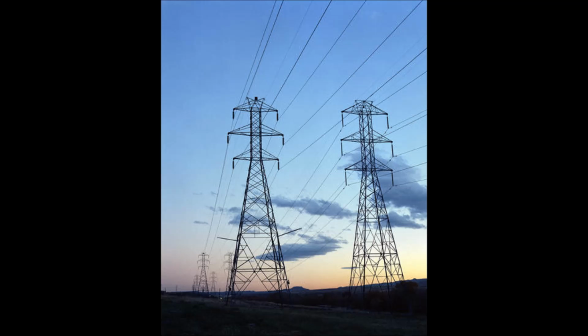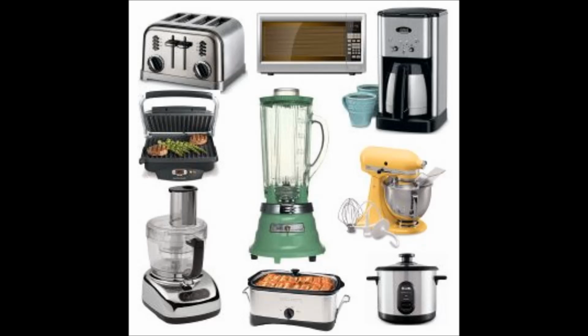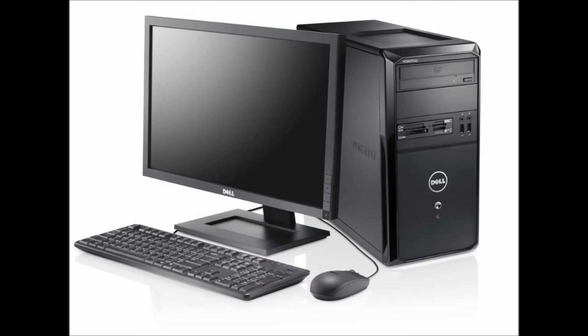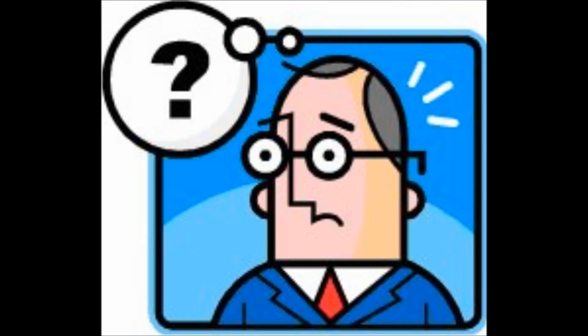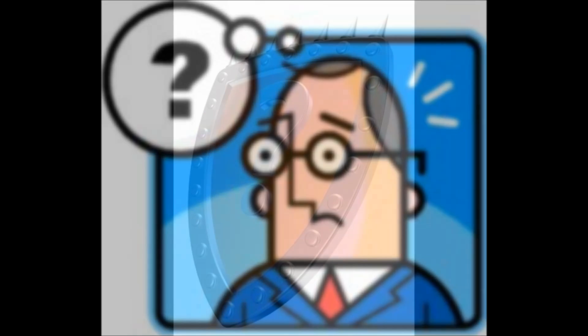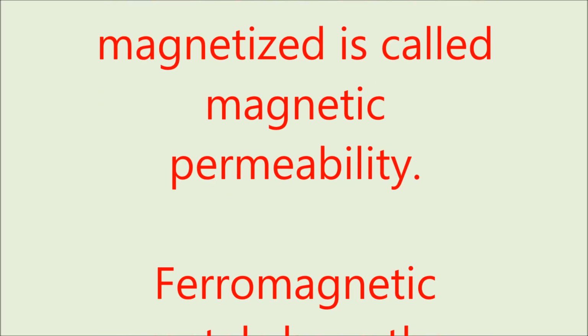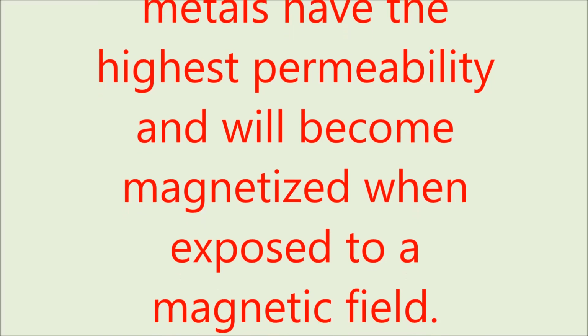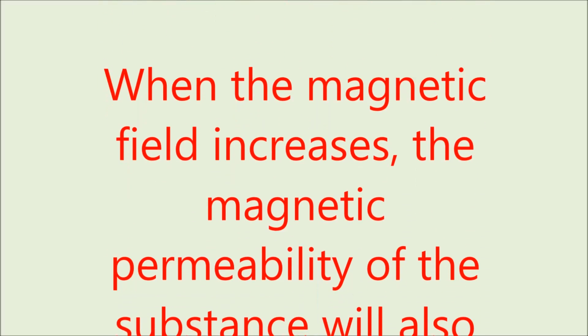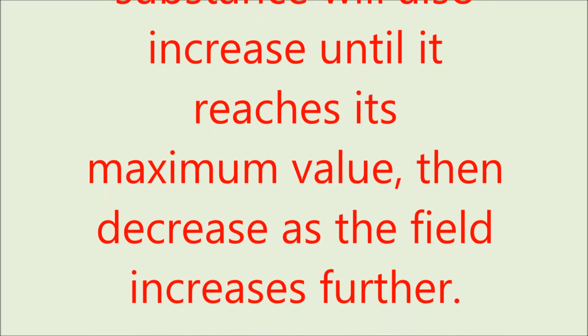Magnetic fields emitted by wiring, appliances, or electronic devices can be a problem requiring correction in the home or office. Designing magnetic shielding is not a well-developed science, and sometimes experience, careful attention to detail, and some trial and error testing are needed to produce the desired outcome. Many factors affect shield performance. Naturally, the permeability and saturation induction of the shield material itself must be chosen carefully, as well as the type of anneal. That is only the beginning.